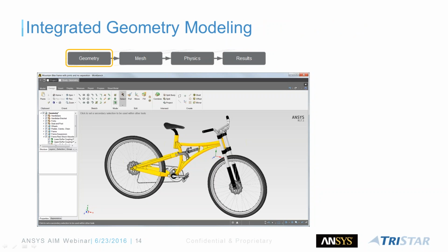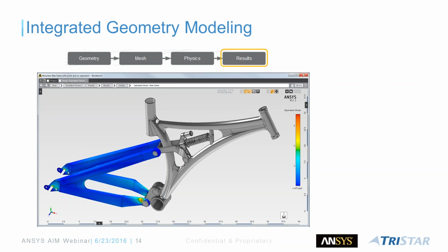So when we say geometry, as soon as I want to edit geometry, it takes you to, within ANSYS, you have this SpaceClaim engine working behind the scenes that's included in the ANSYS license, wherein you can create your fluid volume if you have to. You can defeature, you can edit geometry. So maybe you had a neutral file that did not have dimensions, like an ISO STEP file. You're still able to add dimensions or parameterize it, expose that dimension in ANSYS to create some design exploration. So you could see what happens if I change those input dimension values, and how is it going to affect my stress results or any type of analysis results, right?